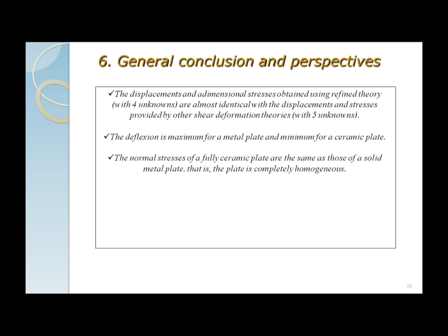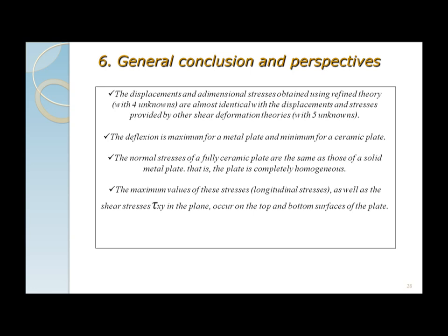The normal stresses of a ceramic plate are the same as those of a solid metal plate, that is, the plate is completely homogeneous. The maximum value of the longitudinal stress, as well as the shear stress tau xy in the plane, occurs on the top and the bottom surface of the plate. When the stress gradient increases, inhomogeneity plays a greater role in the stress distribution calculation.